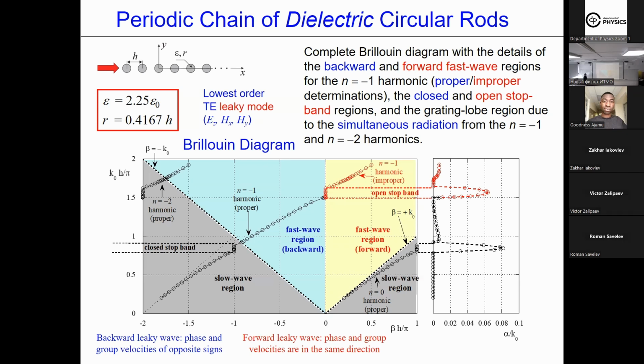my calculation stops when the determinant is satisfied to 10 to the minus 9. It's okay. It's a question of the quality of the solution for a given matrix size. For this calculation, I did not change the space harmonics depending on the region I consider. I have taken the space harmonic number approximately 8. How are you sure that 8 is enough? I increased the space harmonics to, for example, 9 and 10 and checked whether I have convergence, of course.